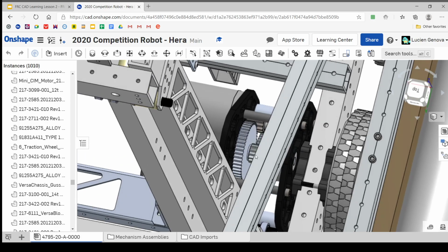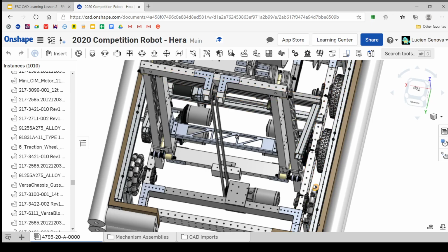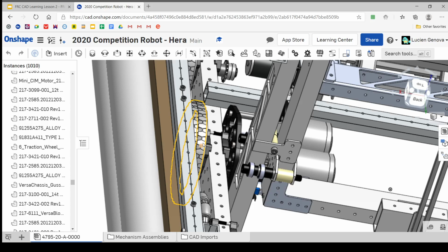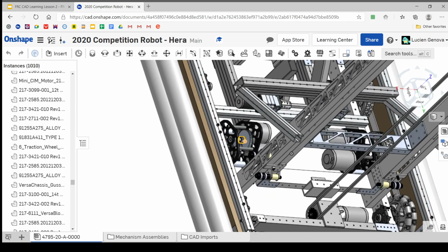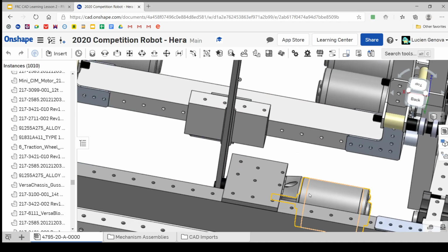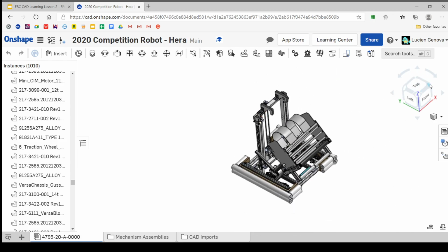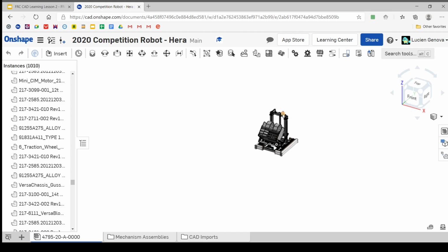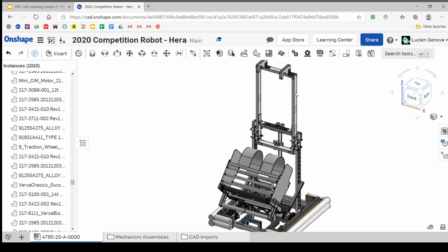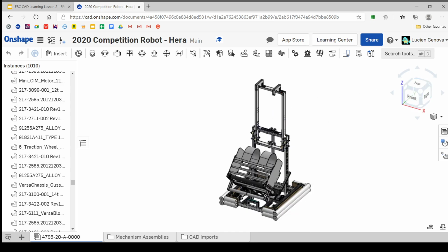And they spin gears, which output to this wheel, which then connects by chains and sprockets to the other 2 wheels. And then you can see we have the same sort of setup on the other side, right? So we can control each side independently and with the same amount of strength. Then you can see we have another motor here, and this actually actuates our elevator so that our elevator can go up and down. All right, lift this up, and that motor is what's responsible. Right? So this will come up, and then this motor will spin the other way, and it'll come down.